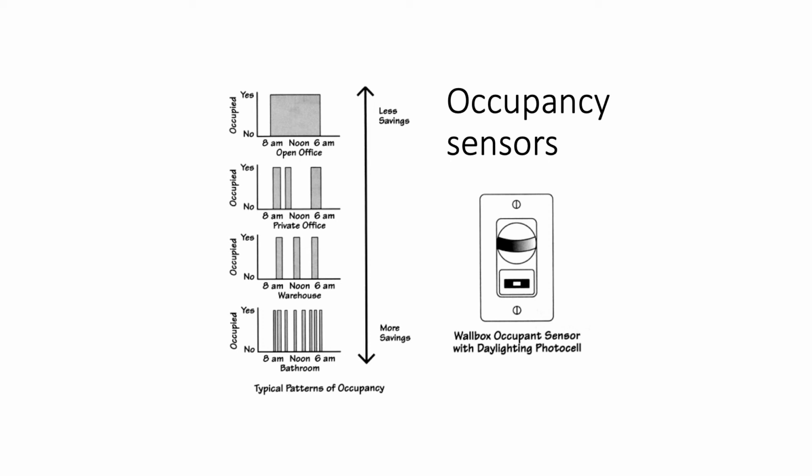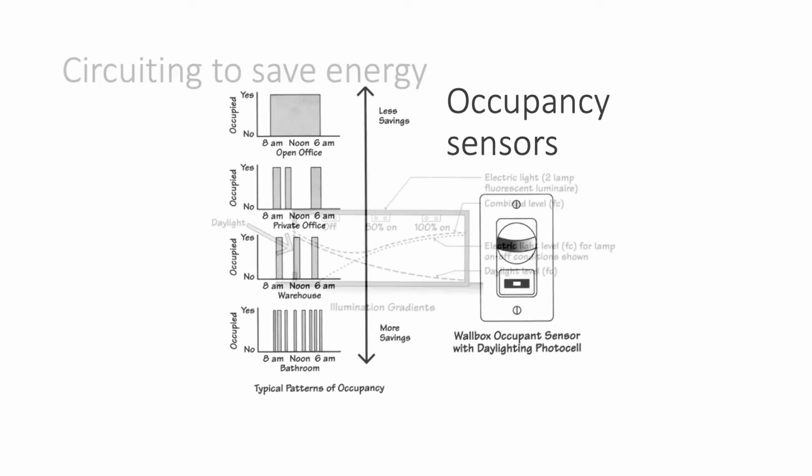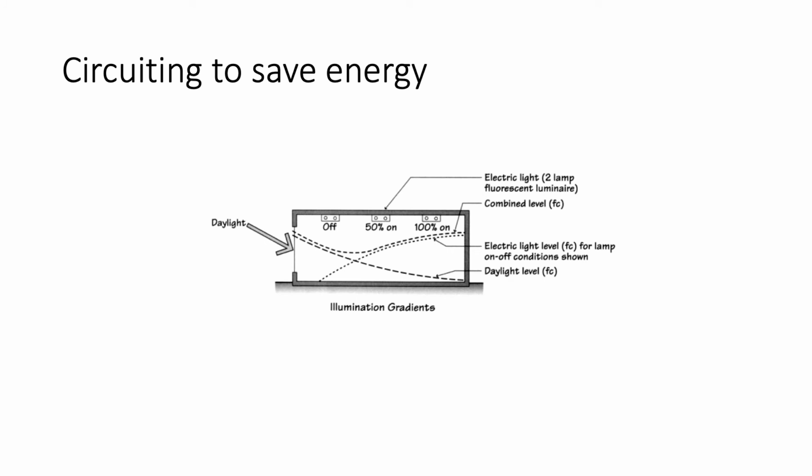They all have a threshold and can be tweaked to be on and off during different times of day. For example, it can be an occupancy sensor during the off hours at work, but maybe just an on-off switch during the normal work hours. Or you can set it to stay on for 5 minutes or 3 minutes or 12 minutes, whatever you want. Our bathrooms have an occupancy sensor, and if you've ever been in the bathroom and the light goes out and you can't get your arms into the sensor's range, it's a little frustrating. So considering how those work is going to help you out.